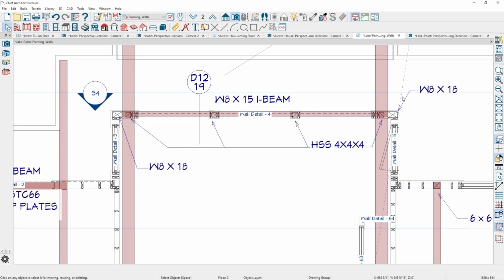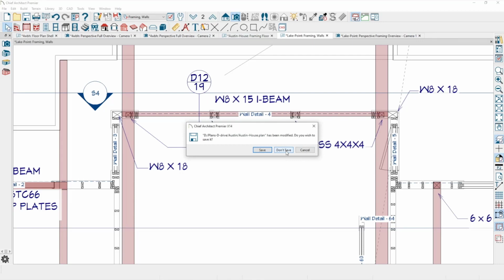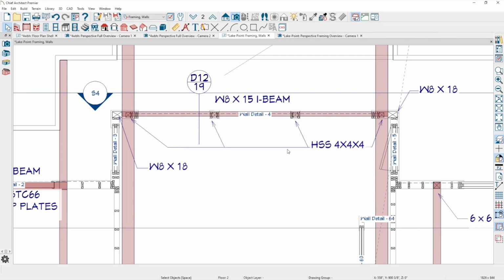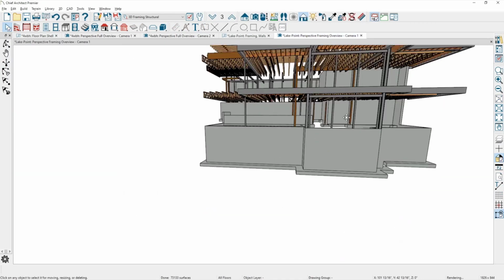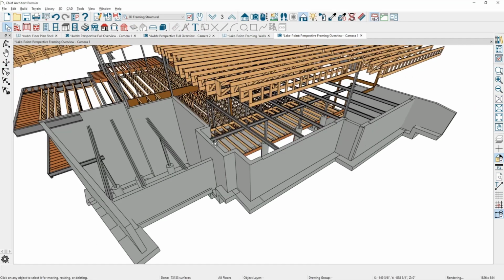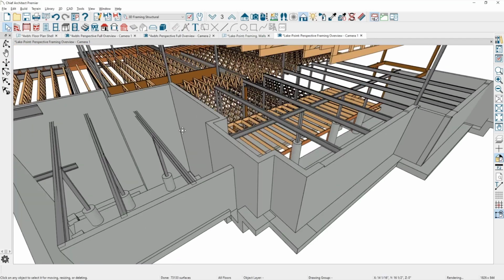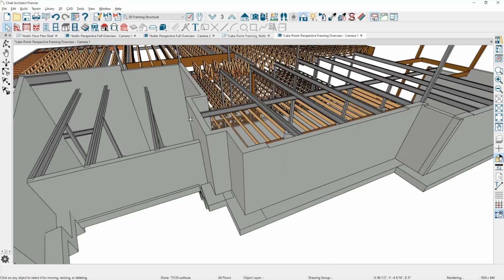What about on front porches? A lot of times we'll put tile on there, or just porches in general. Is there any way to have it show angled joists? A lot of times we'll take a 2x8 and then we'll taper it from 7.5 to 6, to provide the slope on the porch so that it drains correctly during rain.